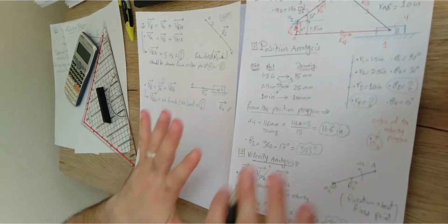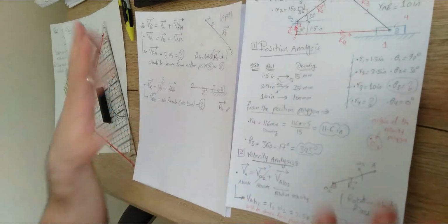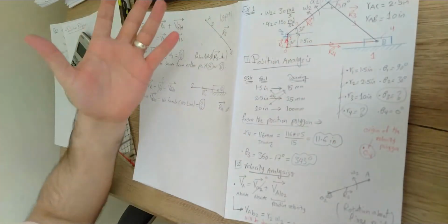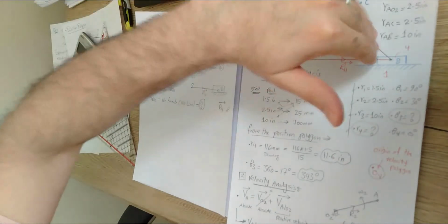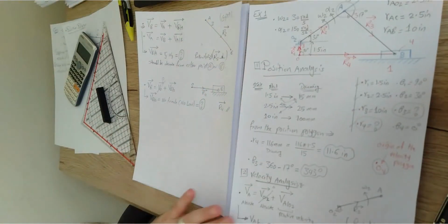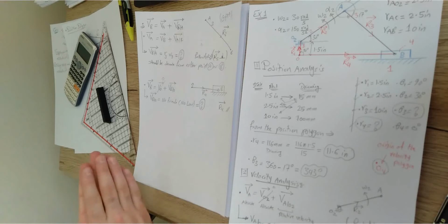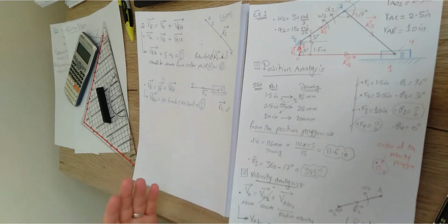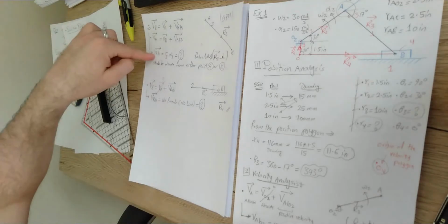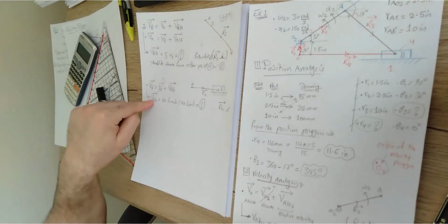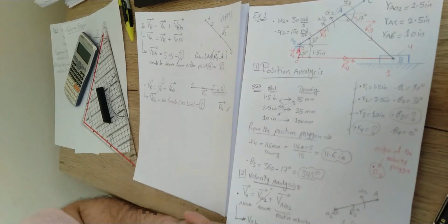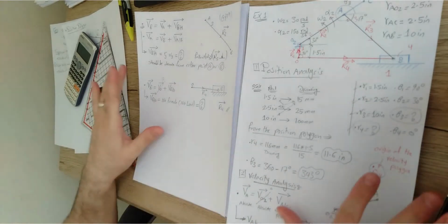So generally, after we finish the slider, there is nothing more. There are no more curves, no more objects, no more elements. We've done link 3, the third link, and the slider. So nothing more. What does it mean? It means that your objective in the velocity polygon is to draw three lines: one line for this relative velocity, one for this relative velocity, and one for this relative velocity. Three lines together define the velocity polygon. Make sense?